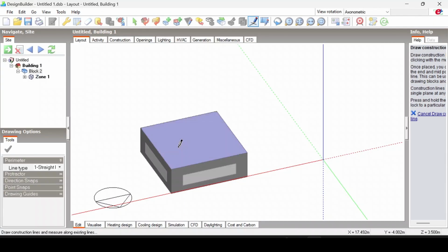So see, it is going here, here. Sometimes if I am clicking on this point, this point is in this face as well as in this face, in this face. So whichever face I am working on, I will hold the shift button, then it is locked. Anywhere you go, just keep pushing the shift button, don't remove your hand. Then you will find every work you do, you will be doing in this face only. So once you have clicked on this face, then you can go to any location.